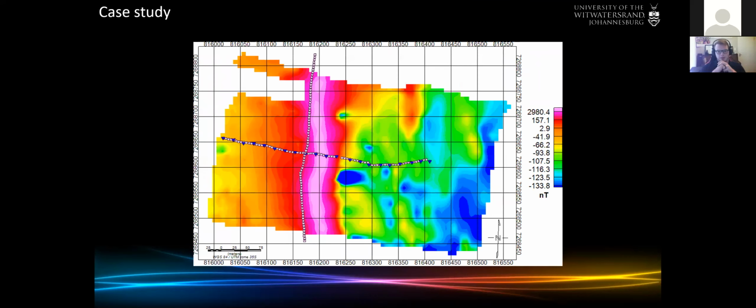So now that we know roughly where the dike is that we would like to test our new method on, we then planned two ERT surveys. So the white is showing where the electrodes would be for the resistivity method. And then the blue is showing where the AMT stations are. So yes, we have about 21 AMT stations with a 25-meter station spacing, which is pretty much overkill, but we wanted to make sure we had enough data to do this test. So this is our general survey, and we really focused on the east-west line here to see if we can see this dike.